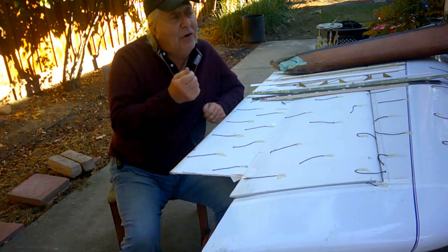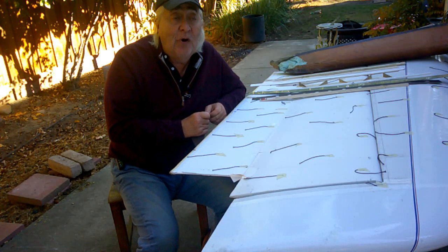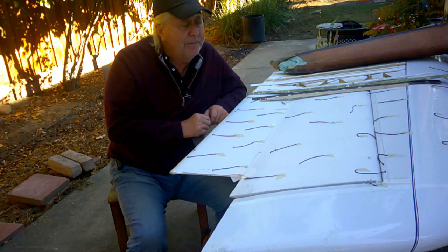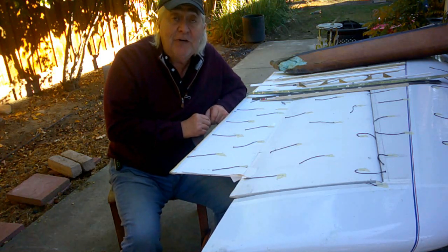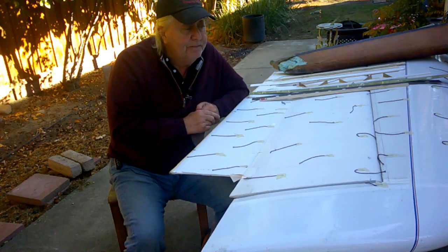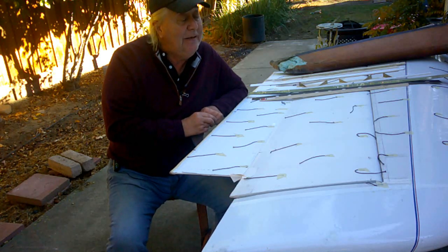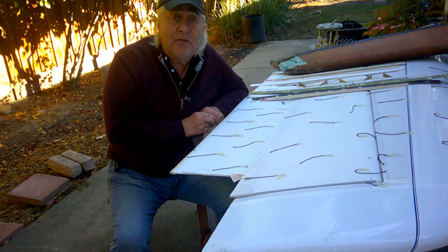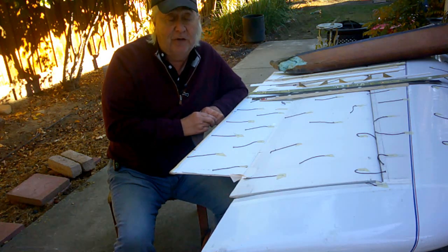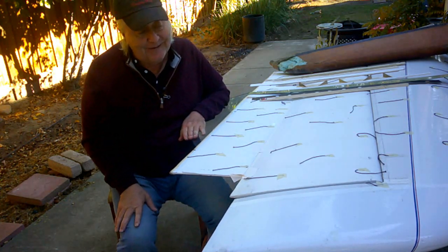That works. I've gone out and tufted the Swift. I know that it'll do 17, maybe a little bit more degrees of down elevon deflection before any separation begins to occur. I also know that it has a turbulent boundary layer across the entire chord of the elevon. Like, wow, Swift gets it to work. How come it doesn't work for me? Well, they are different airfoils. The Swift uses a low Reynolds number airfoil. Why? Because they fly at a low Reynolds number, just like all other hang gliders.